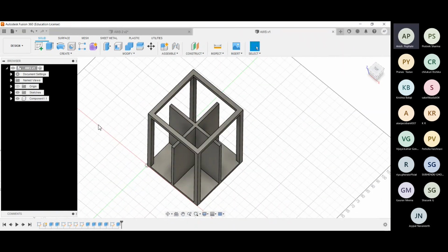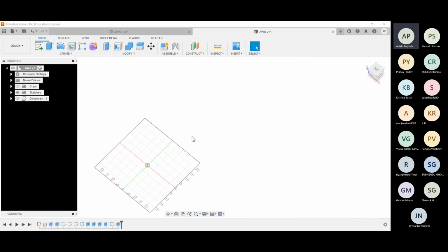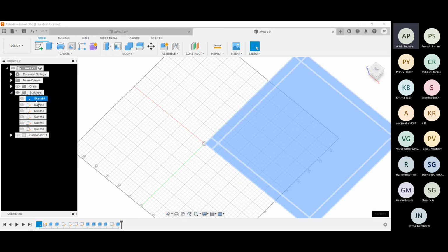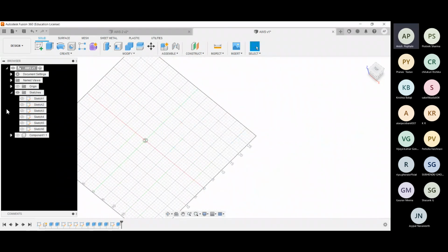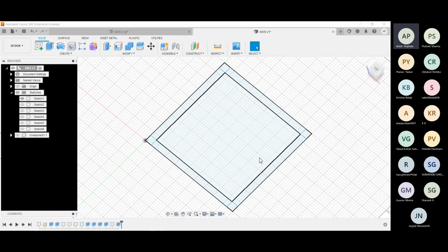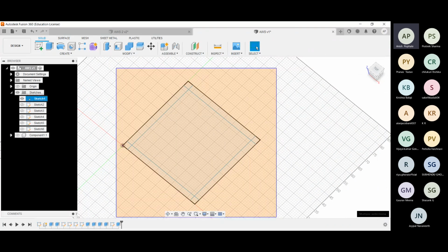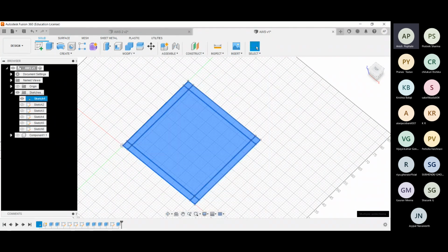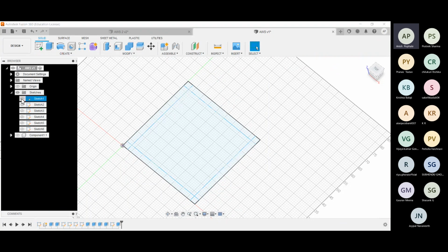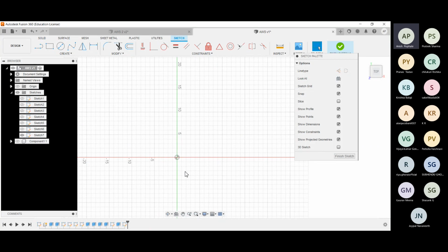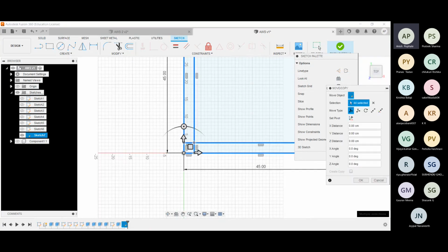For this also we'll try to create another sketch and then extrude it to create that component. The sketch for that will be similar to this, just there will be one circle here and we will extrude different faces. So we can copy this sketch and create a new sketch using that copy. If I select all of this, right click and click on copy, then hide this sketch, create a new sketch and just paste it. I will get the sketch here.